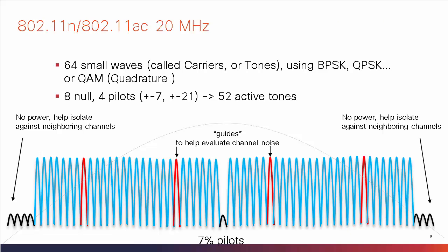When you move from 802.11g or 11a to 802.11n traditional transmission, not what they call the legacy mode, but the real standard 802.11n communication, we still have those pilots. The only difference really is that we move from 48 useful subcarriers to 52 useful subcarriers by basically only flattening out 4 channels at the bottom instead of 6 and 3 at the top instead of 5.